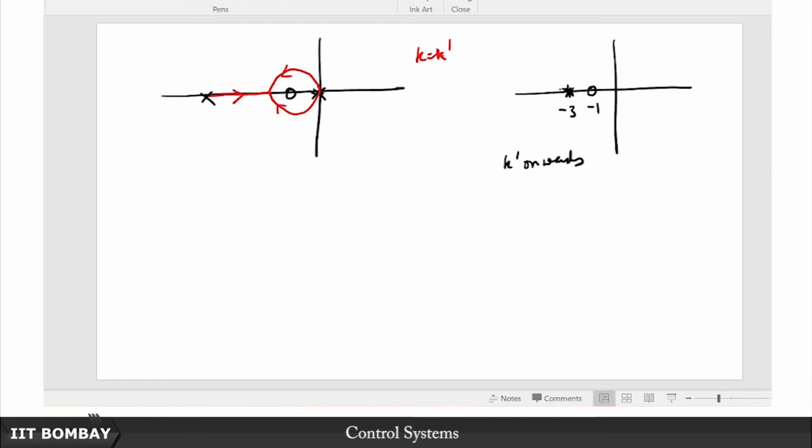So given that that is the situation, now you see there is a root locus segment in this portion, obviously, because there is only one 0 to the right, but beyond this the total number is 4, so there is no root locus. So then it stands to reason that there must be some breakaway and break-in. If I want to find out this breakaway and how it goes, I can again apply this epsilon approximation and I can try to figure out which directions they will be breaking away. How so? Draw this epsilon ball around this.